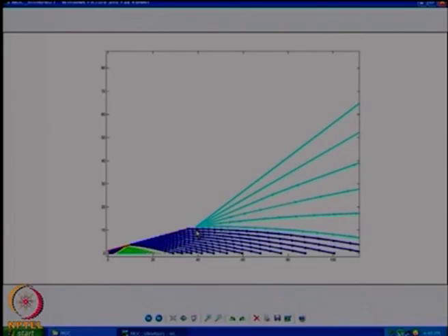Up to here, we did not consider any cases where shocks will be produced. After this, the next characteristic point I have to solve for will be from here, a pressure boundary point, and from there it will just continue as a pressure boundary this way, and you will realize that the plume of this nozzle jet is coming out to be really big along this line. The flow is going to go all the way around up to there. That is what you should be seeing. I did not show you that case, probably I will try and show one picture of that next class.